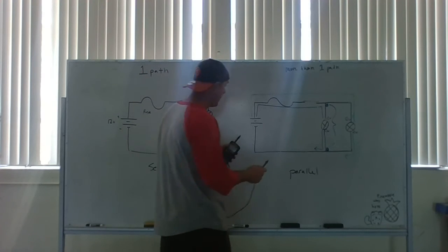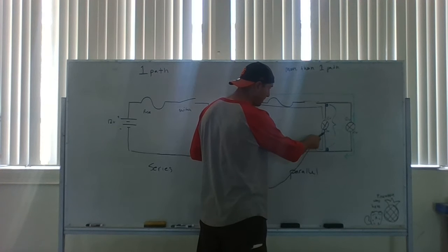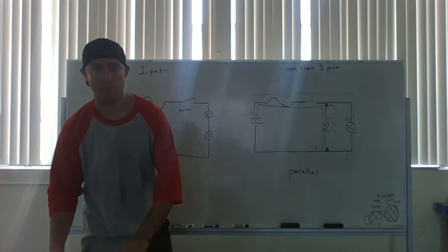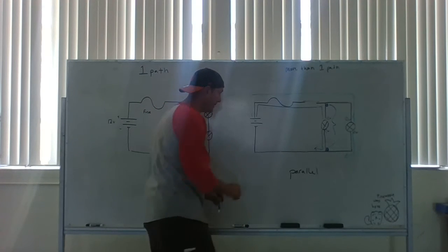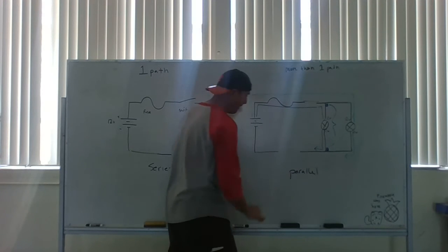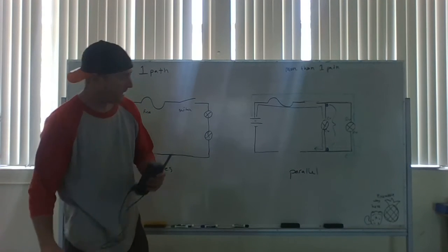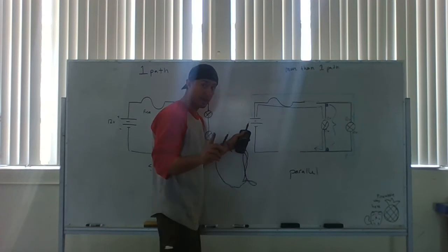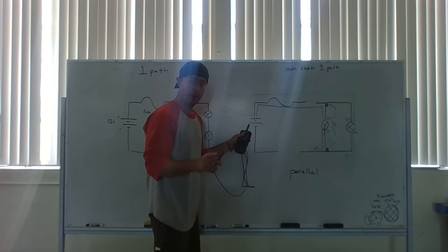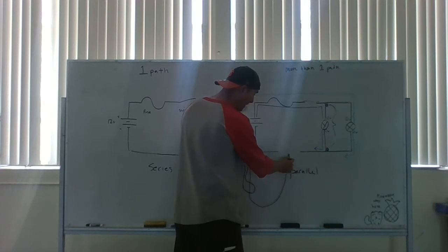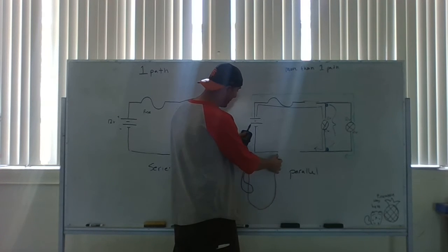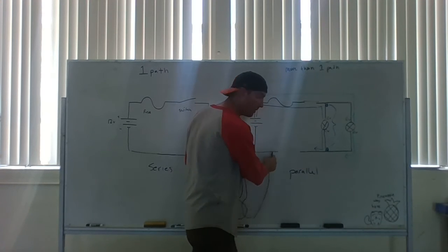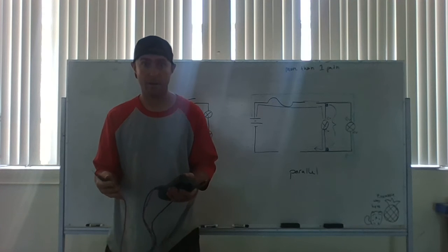So that is what's happening here. I can measure here. If I have 12 volts here and I have 12 volts here, that means there's some problem with my ground path. Because if I have a break right here, I would go ahead and put my meter here. I'd measure here. I'd still have 12 volts, and I shouldn't have 12 volts, but I still have 12 volts there. That means I could keep going down my line to find my break. Then I check another spot down here and I see 0 volts. Okay, there's an issue between that last 12 volt reading and that 0 volt reading. Something's not working there.